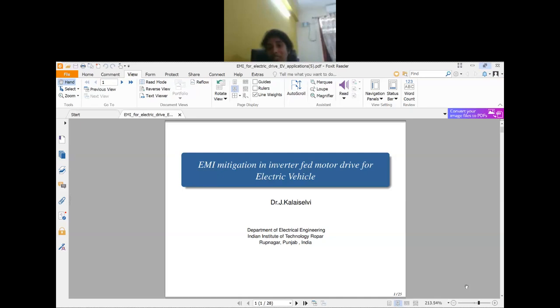The main reason is that for any product you sell, the first thing they would see is how it would affect the grid. We are connecting everything to the common grid, right? So definitely it would have been done. For the adapter you are connecting, there will be some EMI filters inside. The effect would be minimal. Standards they definitely have to meet.